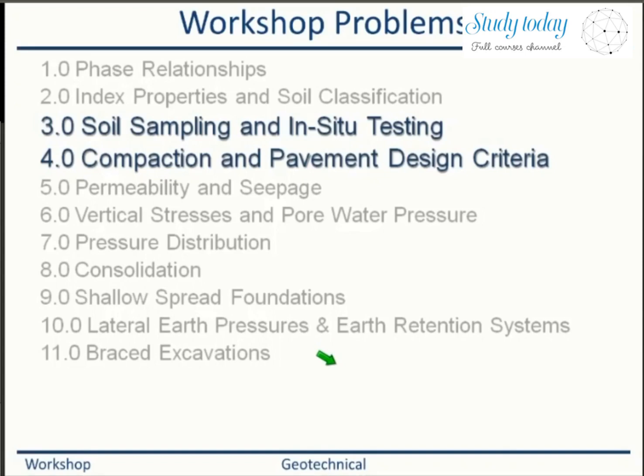Very good. Anyway, please do the testing. Make sure structurally, go to the structural engineers, so they make sure your building is sound. Minor cracks may not be a big problem, but if you have a shear crack, which is a prominent one, you should let the structural engineers evaluate it. For me, one story or two story should not be a big problem.